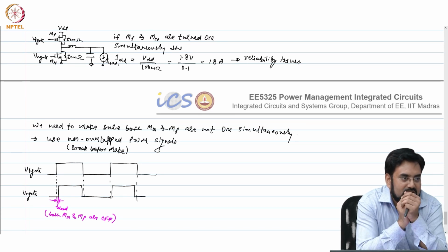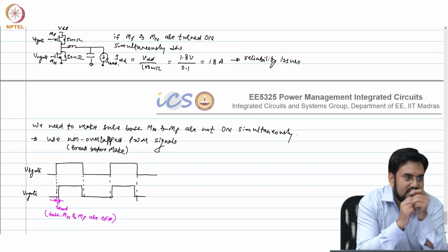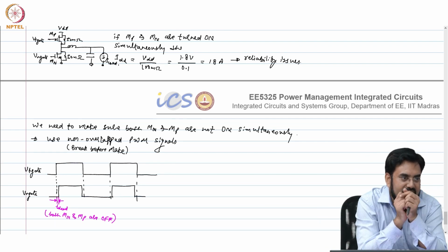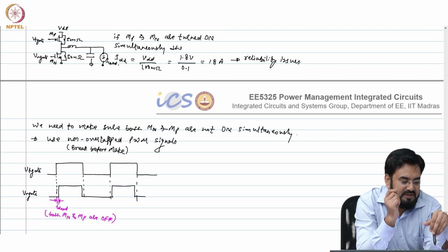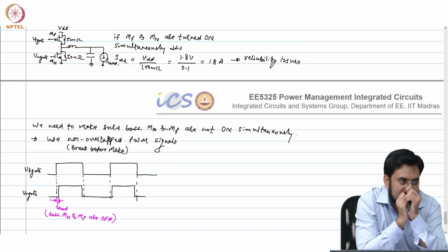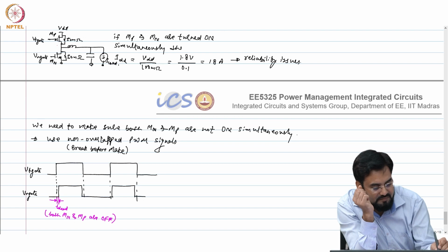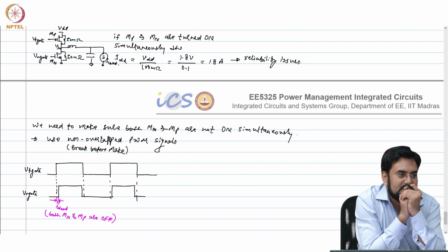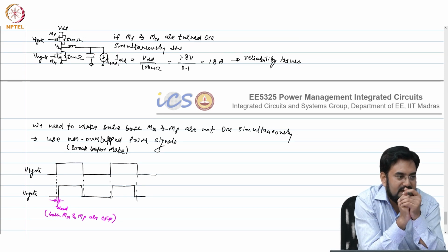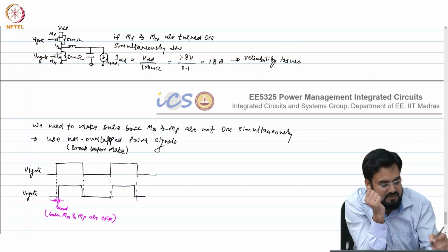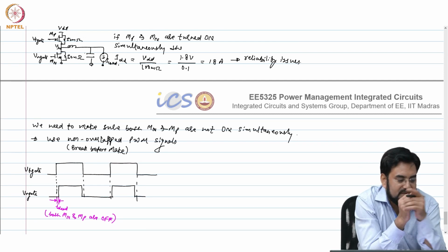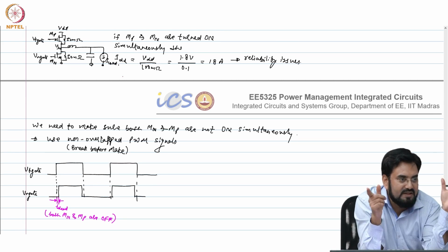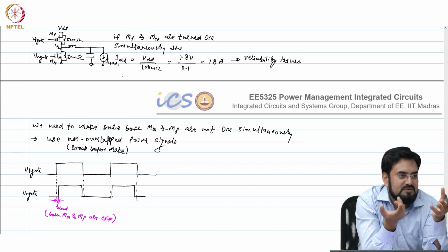It won't go to zero because it has some slope, an RC time constant. So it will rise and fall based on the voltage. So if you leave the other node, VSW, as high impedance, and the current is still flowing into it, say the load current is 1 amp, which was flowing through NMOS, and you turned it off, that 1 amp will keep flowing for a certain time, unless the voltage across the inductor falls to zero.